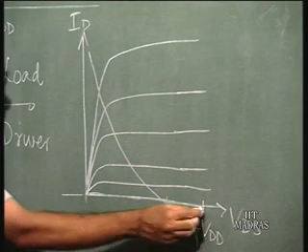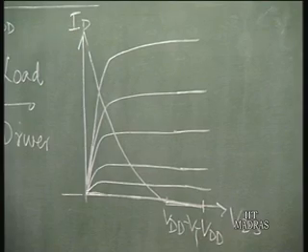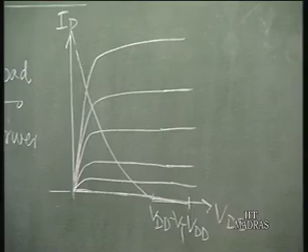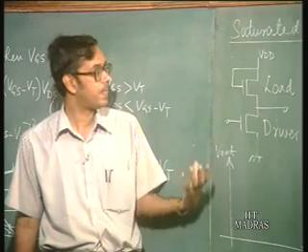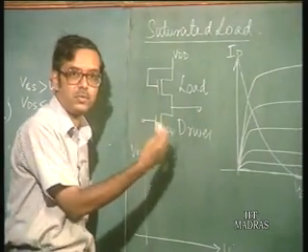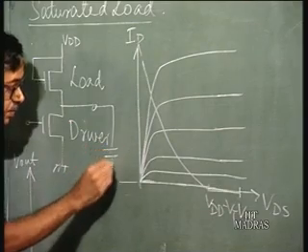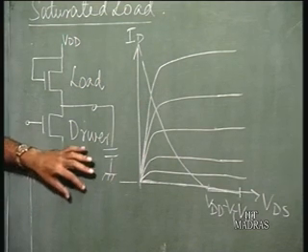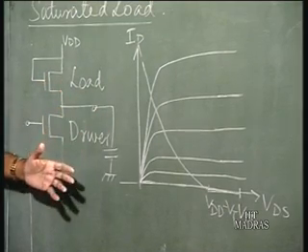So, it intersects all along this. What is going to be the output voltage, whether it is going to be VDD or VDD minus VT or somewhere in between? That is the question. Now, when you want to discuss that, what we should bring out is that we have not brought any capacitance into the picture, because we are just drawing the static characteristics, but usually these devices will have a capacitive load, which may be the input capacitance of the next device.